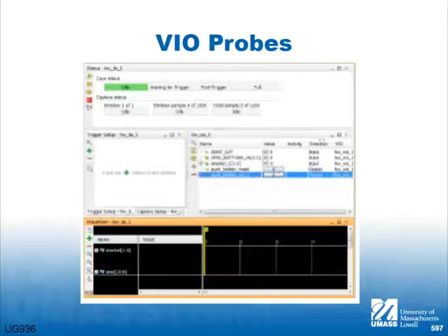But when you come up with a new kind of algorithm like this, what you do is you effectively have a value and you walk an error through it. So if you have a 32-bit value, you flip the first bit, the second bit, get the idea, right? Then you go to the next value and walk it through, and walk it through. This is a difficult process, and it's impossible in simulation because it's too slow.